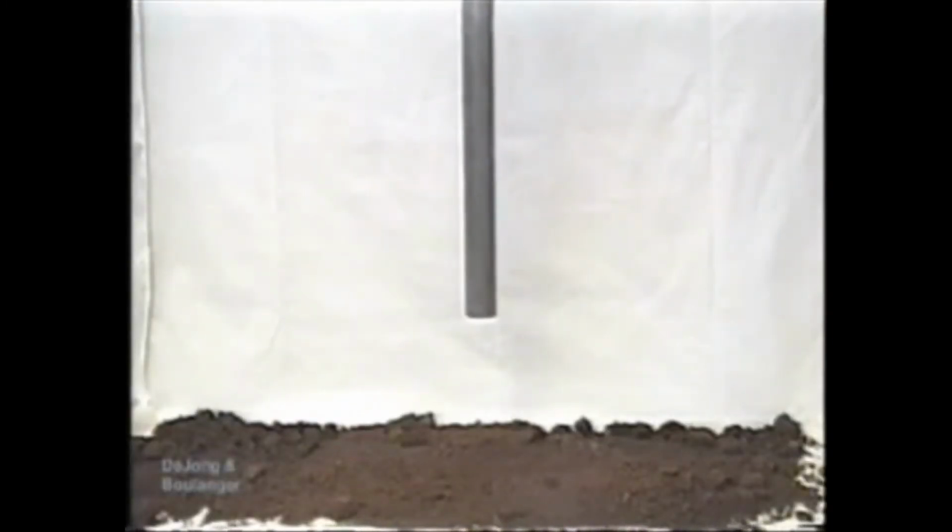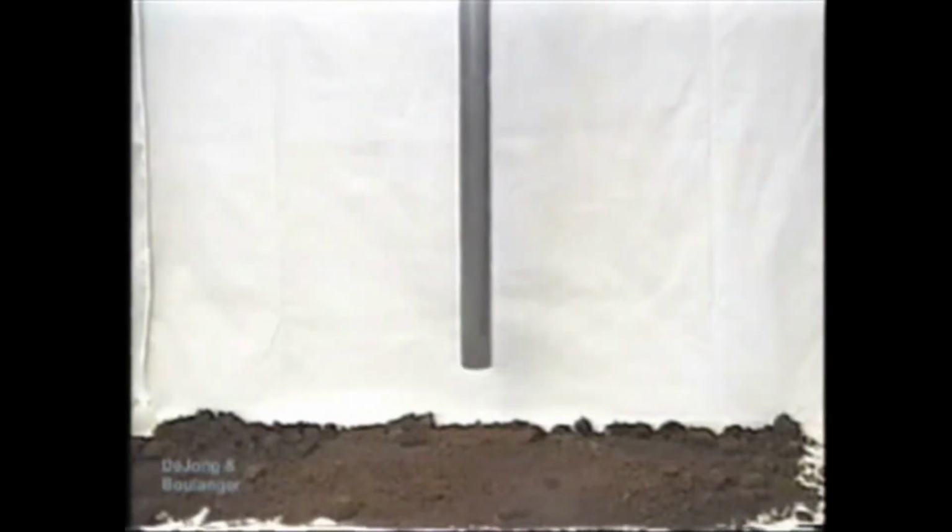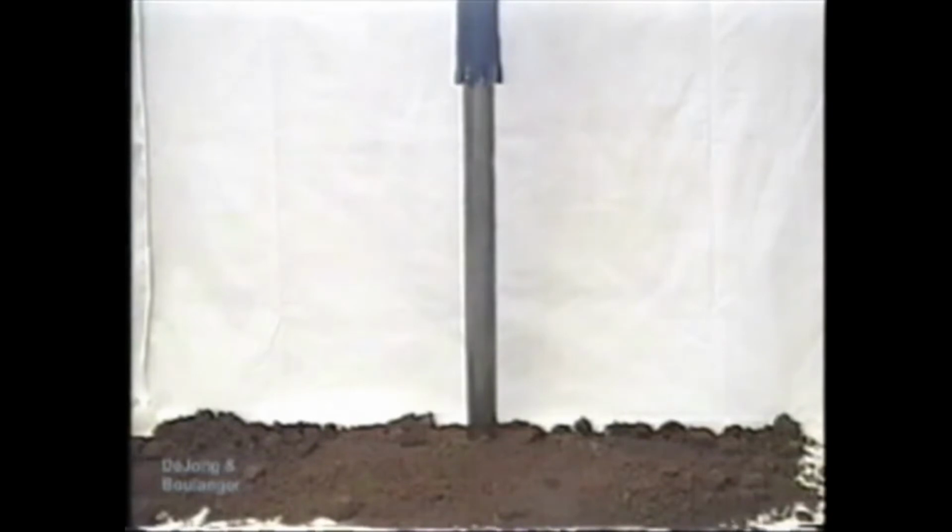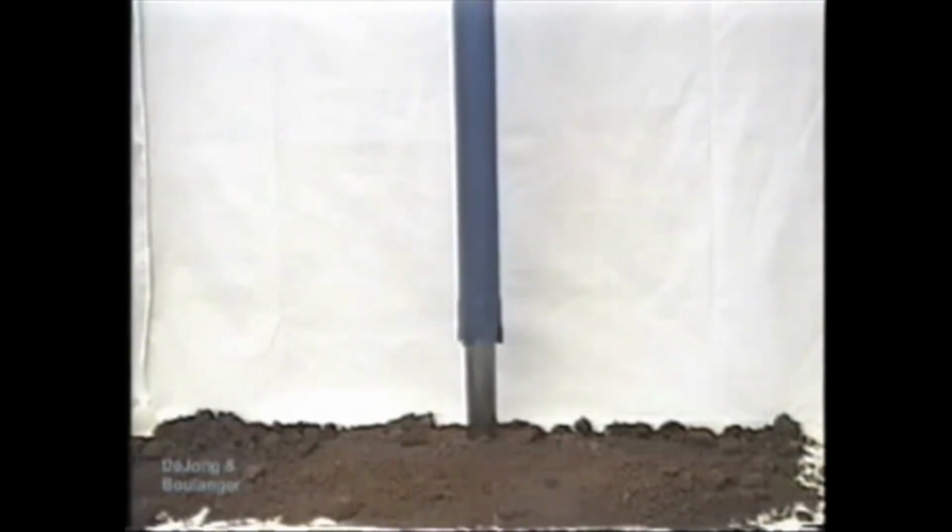samples. While the pitcher sampler is being lowered into the hole, the thin-walled tube is suspended from the cutter barrel, and drilling fluid circulates downward through the tube and flushes the cuttings from the bottom of the hole. When the tube encounters the bottom of the hole, it is pushed upward into the cutter barrel, while the circulation is diverted outside the tube into the annular space between the tube and the rotating cutter barrel.